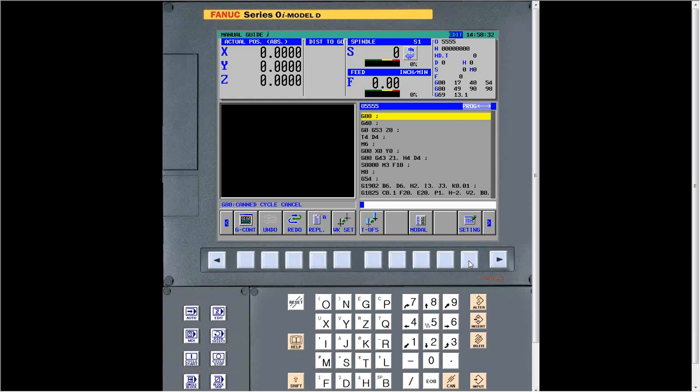Not necessarily how I want you to set it up, but the way you want to. Within your fixture forms, and I've had several people do this, they actually download their Renishaw probing cycles, so they're usually relatively short, and they put them in their fixture form. And then, when they're doing their programming, they'll just go grab one and insert it right into the conversational programming and use it right within Manual Guide i. Okay, so it is capable of doing that.